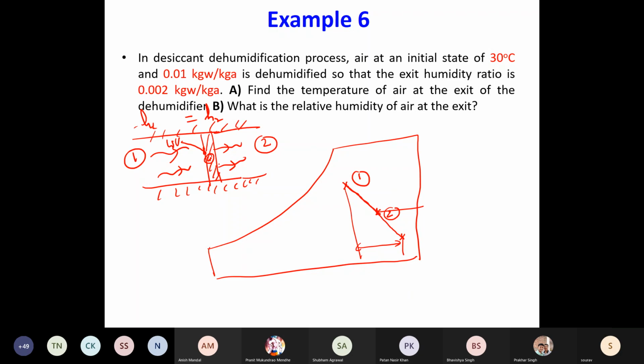It has to go to the incoming air only in the steady state condition. Definitely, it will also warm up the desiccant wheel, it will warm up all the ducts. So this phase change process from water vapor to liquid water is what is raising the temperature of the incoming air. So what you get at the exit is hot but dehumidified air.